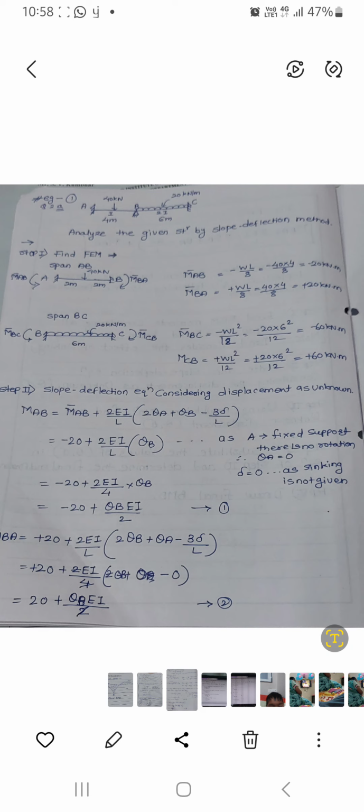Okay, so here in this case, the continuous beam is given to you, and in this continuous beam, we have the supports A, B, and C, where A support and C support both are fixed ends, and B support, which is an intermediate support, is a hinge support. Now in this case two types of external loading have been given to you. One is a centrally acting point load, and another is the UDL, that is uniformly distributed load, of 20 kilonewton per meter. And here, the span length for AB is 4 meter, and for BC it is 6 meter.